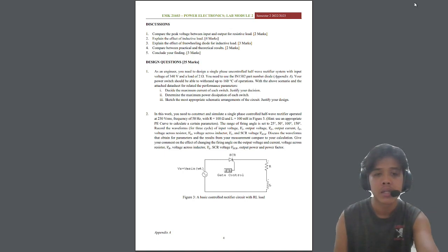The circuit will be powered by the voltage supply for a positive cycle due to the impact of an inductive load. Inductor charging occurs as a result of the supply voltage and the diode's forward bias. Reverse bias caused by the diode to open circuit later on in the negative cycle. So the diode changed into forward bias once the inductor became the circuit supply. Then the diode becomes reverse bias again and turns into an open circuit with no supply up until the time at which the inductor is fully discharged. As it resumes the positive cycle, the waveform repeats.